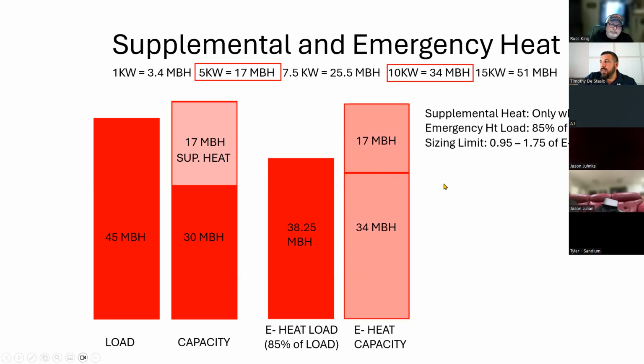Either way, if you stage it, your heat pump is only going to use what it needs. I mean, the worst thing that's going to happen is it's going to cycle off. Big deal. So don't get wrapped up in trying to figure out the exact kW you need, because you only have a few choices that you can pick out from the supply house anyway.